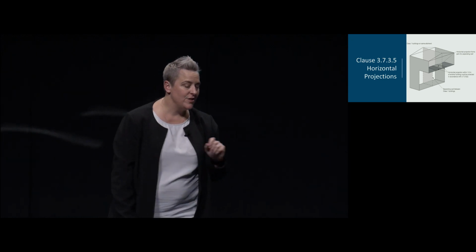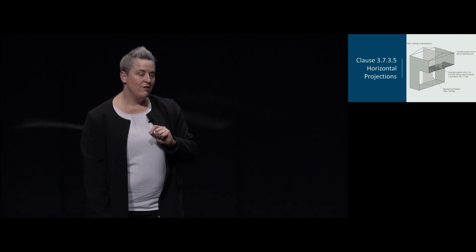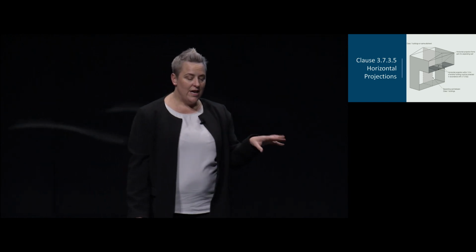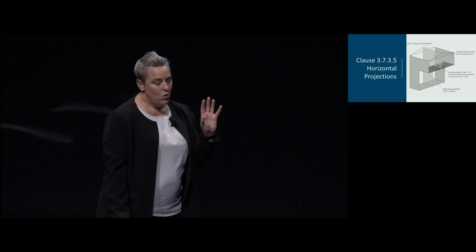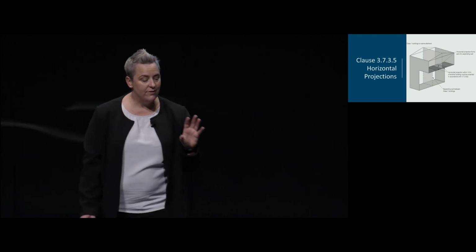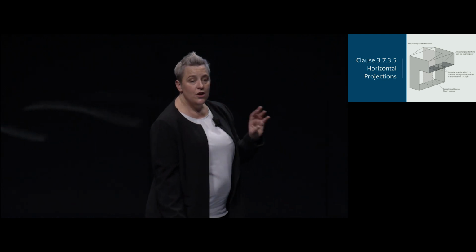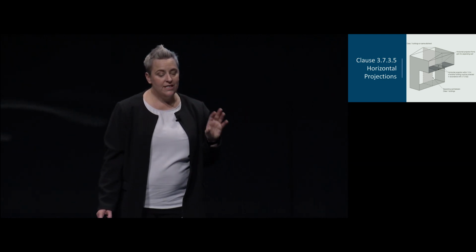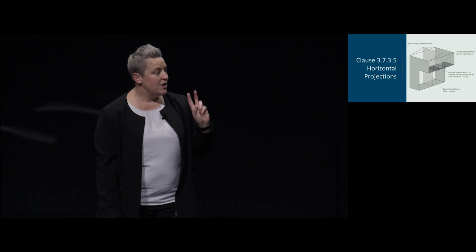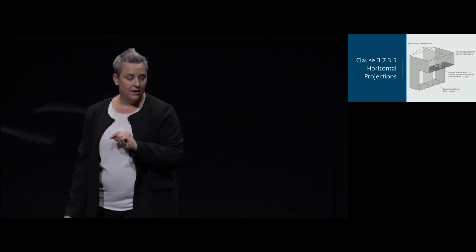Or you can have a fire protective covering on the underside of the floor if the floor is combustible or metal. So the fire protective covering is a defined term, and it can include a 13mm fire protective grade plasterboard or a 12mm cement sheeting.